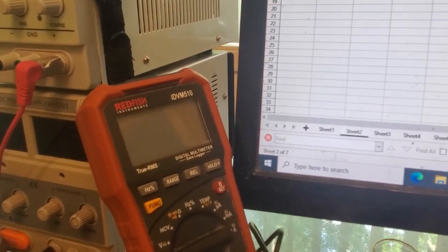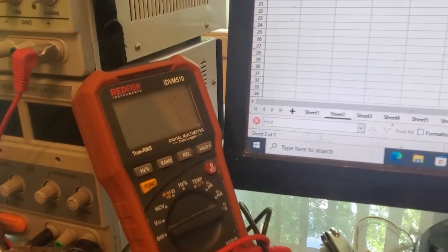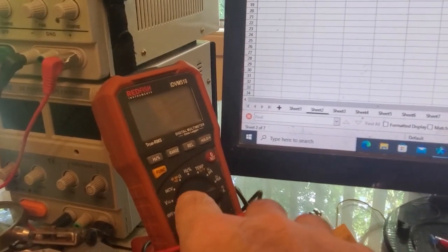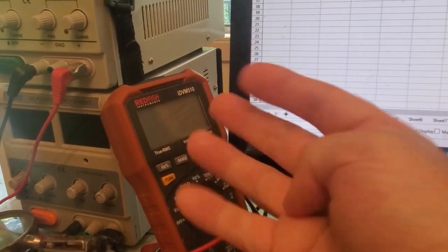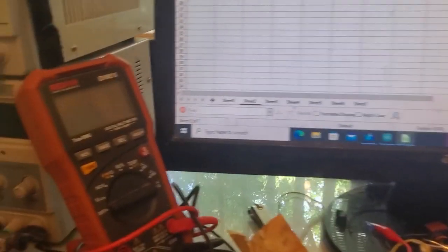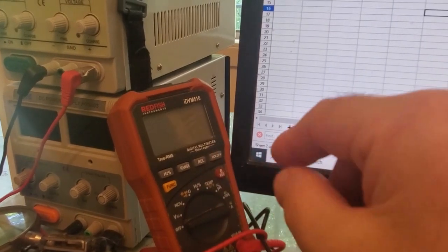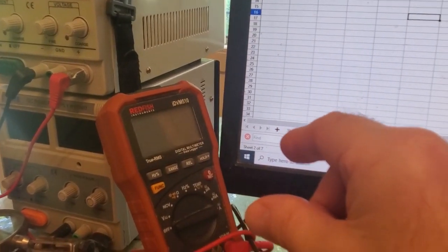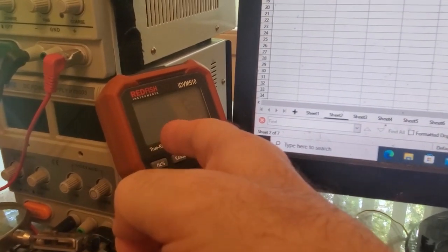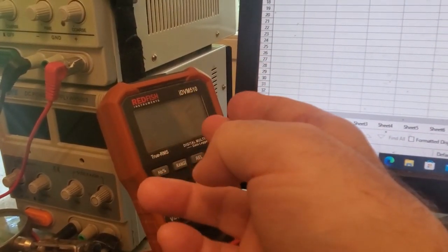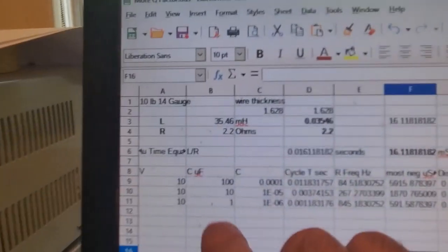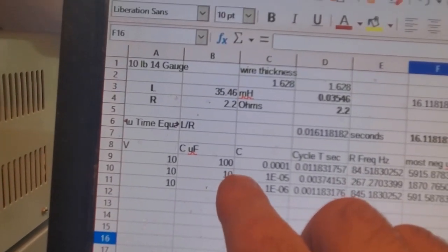So what I did was I ordered 10 mega ohm resistors off of Amazon. And the thinking was, instead of having 10 mega ohms, I'll put 9 10 mega ohm resistors in series to make the resistance in total 100 mega ohms, all the readings will be 1/10 as high. And what do I care? So instead of 10 volts, now it reads 1 volt. It'll actually give you another digit of precision. And now you could measure this 1 UF cap the same as 10 UF.